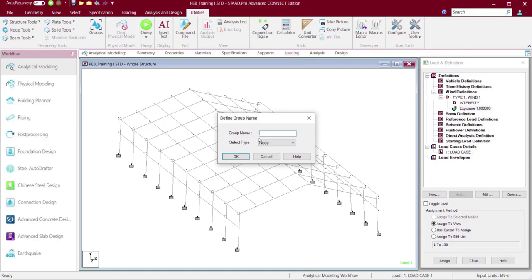So next, we have only defined a single wind load definition, type 1. Later on, we'll see if you want to add one more wind type for the orthogonal directions. But my wind definition is over. Now next, I'm going to define the dead load. Now dead load is simply the gravity load, which is attributed to the member self-weight, and if there is any kind of load which is sitting there forever, then it will be taken as the dead load.